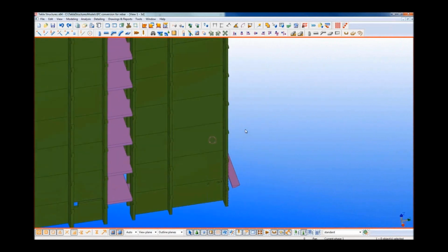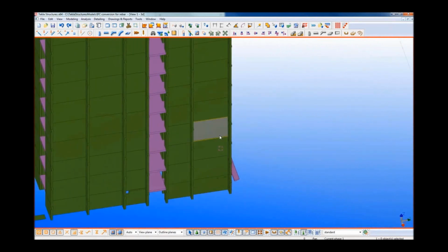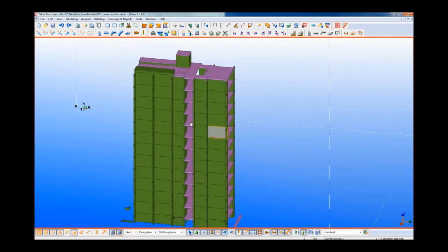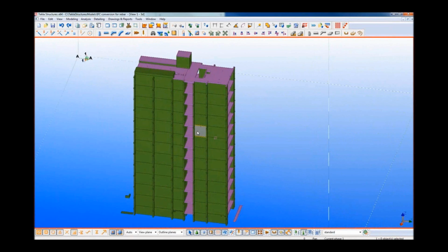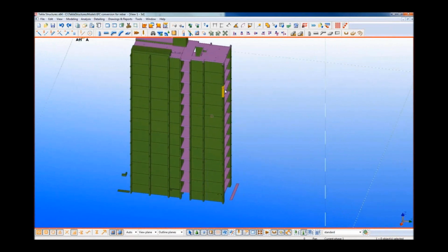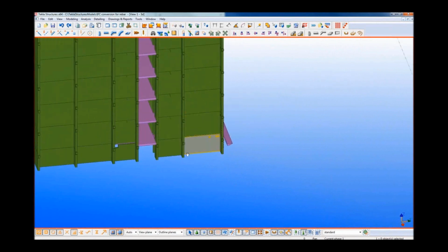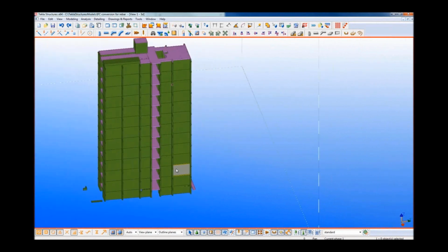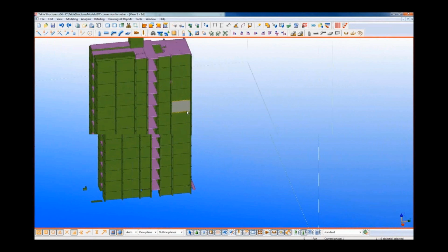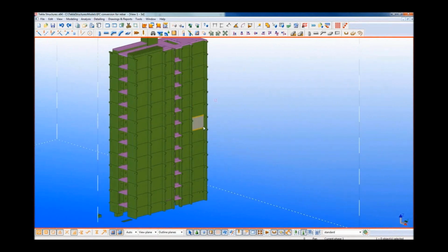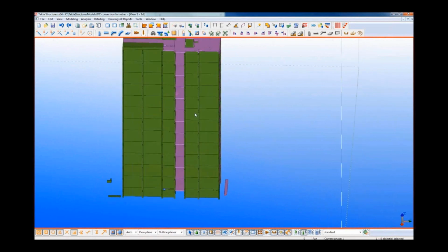And then the next thing you've got to really think about is what do you want to appear on a drawing, the drawings that are going to be the rebar drawings. So the next stage is to bring it together in the form for drawings. We don't want panel drawings of just one panel. We're going to want a drawing of this entire wall probably, and then one of this wall down here and the other. So what we have in Tekla is a cast unit system.